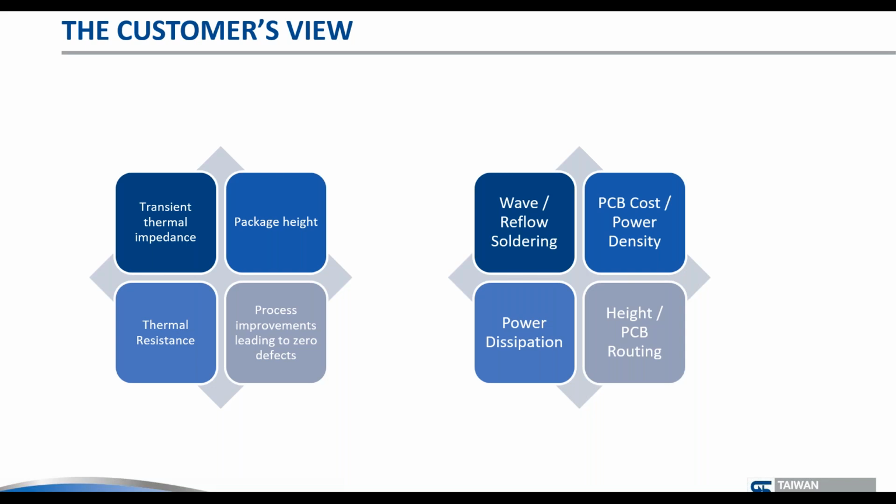We have customers that are willing to use 4-layer PCBs with thermal vias. For other customers, the market is so cost sensitive that they will never even touch these things, and it will stay 1-layer with the bottom of the FR4 just as a big copper plate, or just a few components placed in wave soldering. So everybody's different, and we do not want to influence you.